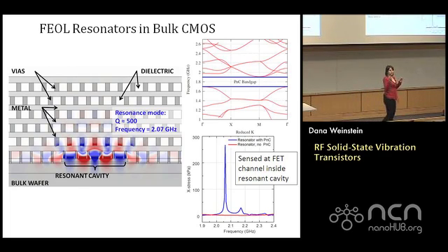And if I define that band gap, I can define a region where, at a particular frequency range, elastic waves cannot be transmitted through. So they're going to be reflected back down onto the transistor. And I can do that coherently.